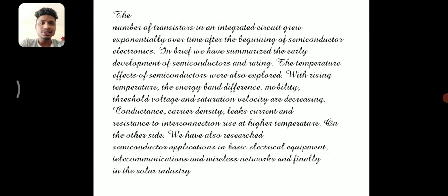The number of transistors in an integrated circuit grew exponentially over time after the beginning of semiconductor electronics. In brief, we have summarized the yearly development of semiconductors and its rate. The temperature effects on semiconductors were also explored. With rising temperature, the energy band gap, mobility, threshold voltage, and saturation velocity decrease. Conductivity, carrier density, leakage current, and interconnect resistance rise at higher temperature.